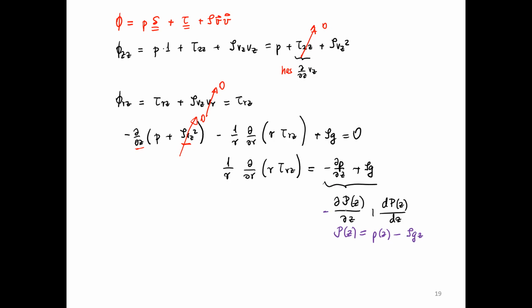So then this is, apologies, minus dP dz. So this is my flow potential. Really it's just a shorthand notation for the pressure that includes both the thermodynamic component and the hydrostatic one because of the weight of the fluid, together into one sort of generalized pressure or flow potential.